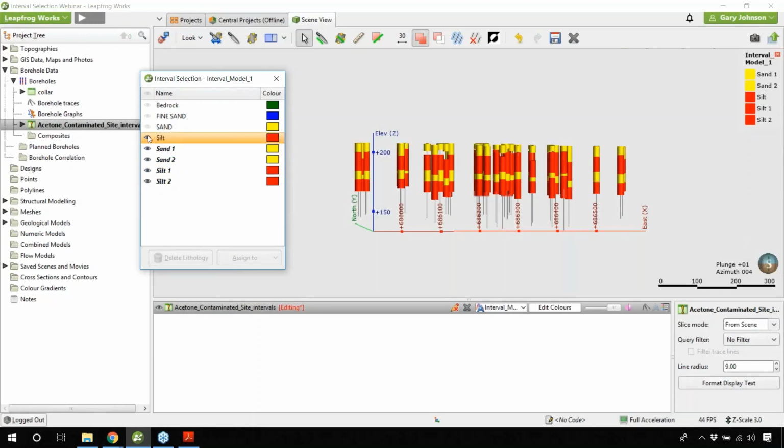One thing that you will note is that you can see all of the lithologies that I have created. You're actually going to have more control over these lithologies than you do over the identifiers that are imported with your boreholes. If you double click on Bedrock, for example, you'll see you can't edit the name, and you can't delete anything that has previously been imported with the boreholes.